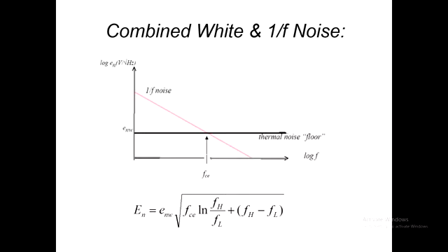It's not included there because I have said here that FH is the noise bandwidth. People get loose with it. You can either say it's a signal bandwidth, or you can say it's a noise bandwidth. In the question that we posed here, this one that I just did the solution for, we were predicating that on a stated noise bandwidth.